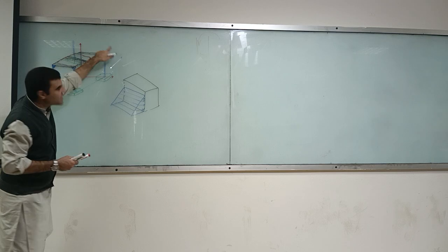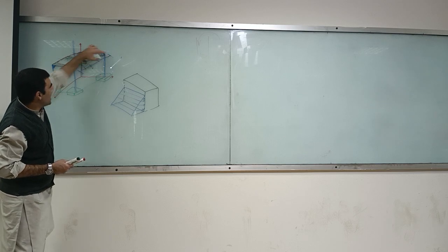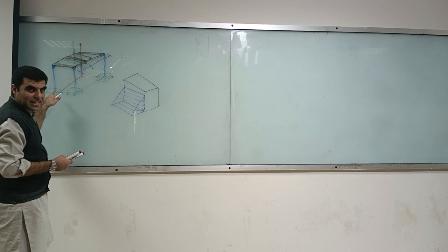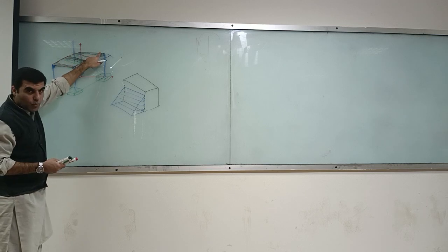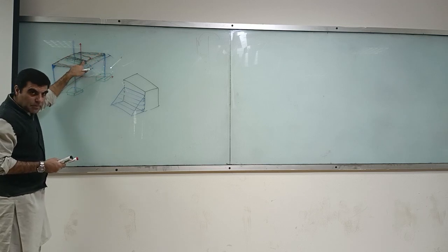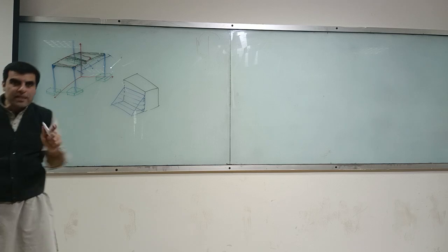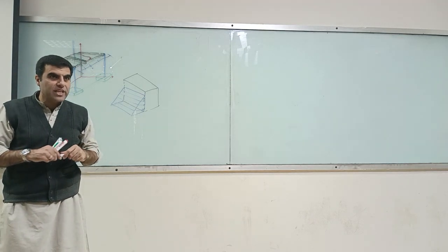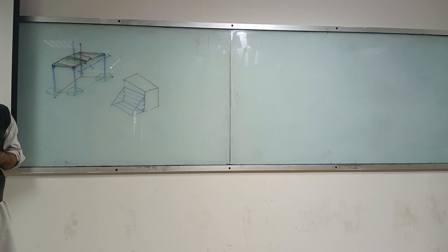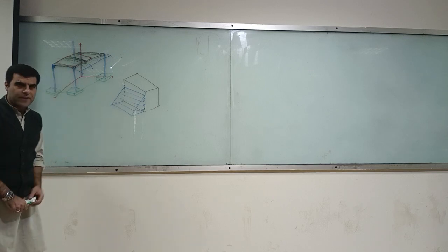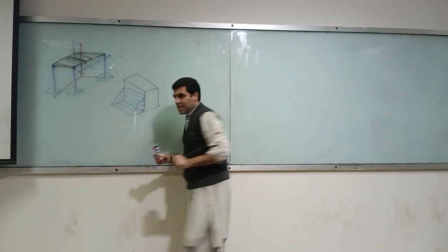For this beam, because there is nothing on this side, I'll just take the one side which is this half, and similarly for this side there is nothing on that side, so it's only one-sided load which is running into these end beams. However, on the middle beam you have got tributary load coming from both sides. So that's how we normally do that, but you can do some FE analysis to find out what actually this length is if you want to dig deeper into it. So that's how normally we do it. But for normal calculation, I think this assumption is fair enough and it gives you good results. So this is one scenario where you can have linearly varying load.